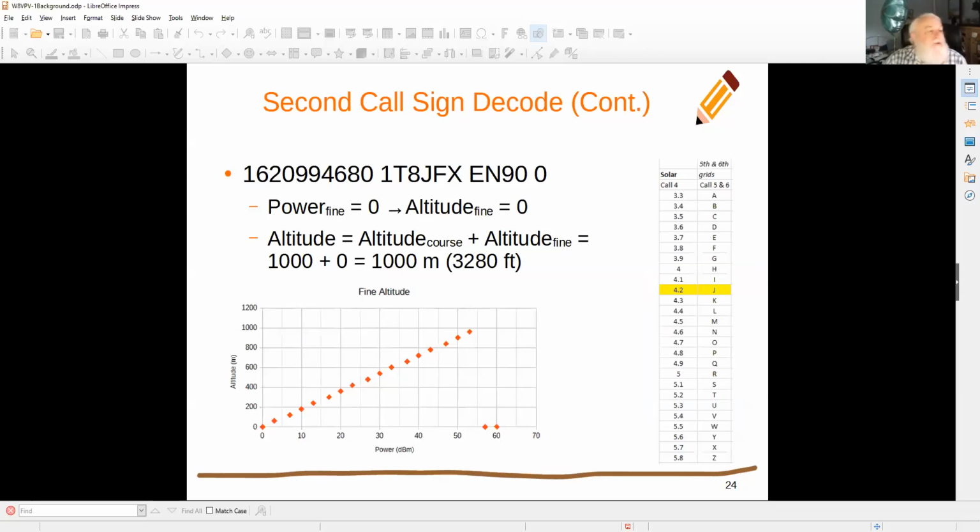Well, the difference here is that in the first balloon, we were using APRS, which required us to be in range of an iGate. But with this balloon, since we're transmitting on WSPR and it's on 20 meters, we no longer have that limitation. So since we're transmitting on 20 meters, we expect to have, and so far are seeing, transmissions from all over the world. So that should not be a concern.